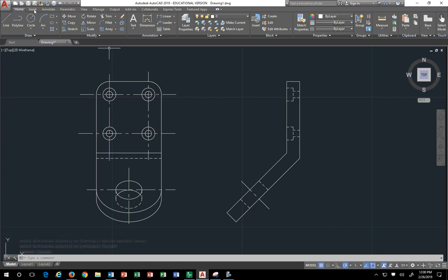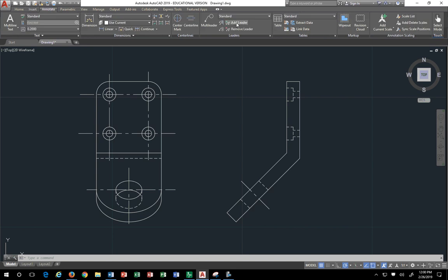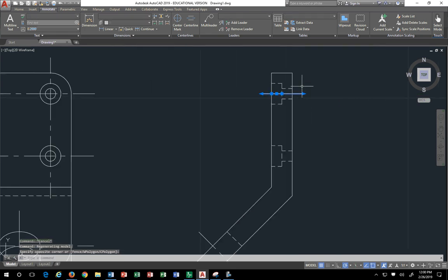Here is probably where I would say it's six of one, half a dozen of another if I use the center line function right here. If I do, I pick the two lines that represent the center of the object. Now what do I have? I have a line. I don't like it. If I extend it, it doesn't turn into a center line. So I don't like it.